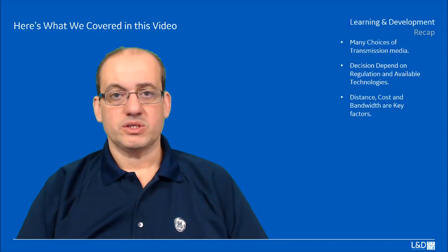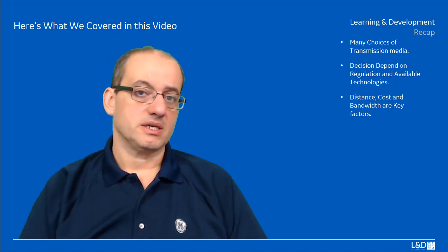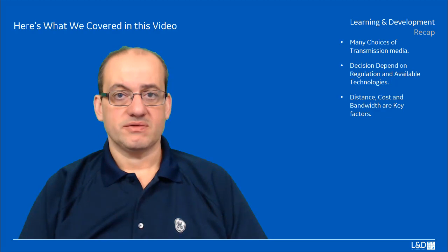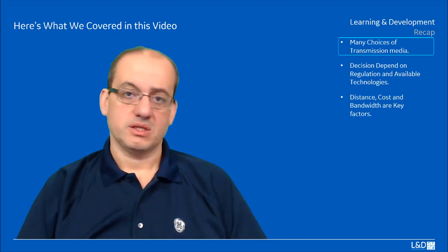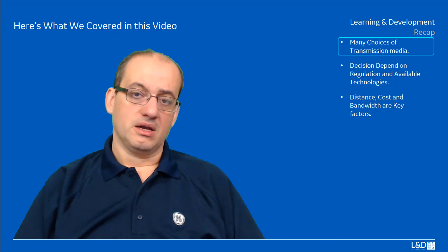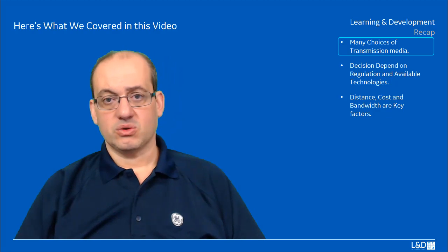Thank you for taking the time to watch this overview of physical available connectivity between the remote terminal unit and the control centers. Obviously, as technology advances, there will be more options. Today, we have seen the many choices of transmission media: the coax, the wireless, the data, and the voice. And there is a lot of effort in the substations right now to not only monitor the data, but also have visuals inside the substation. So cameras will be installed inside the substation, and data is transmitted using the available media, not only SCADA data, but also video data all the way to the control center.